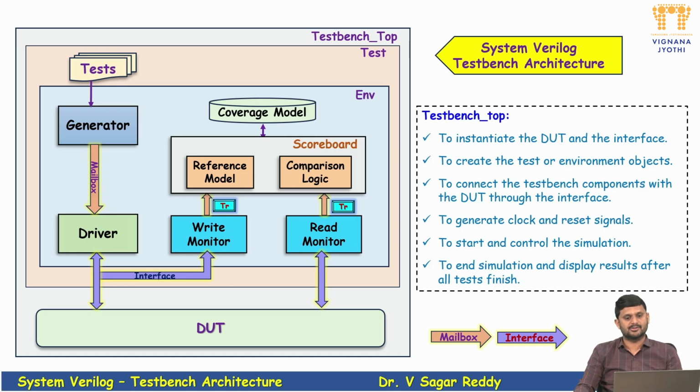The monitors observe and report, and the scoreboard checks correctness automatically. The coverage model ensures completeness. The test controls the scenario, and the Testbench top architects everything. Master this architecture, and you are ready for UVM, industry projects, and a serious career in VLSI verification.